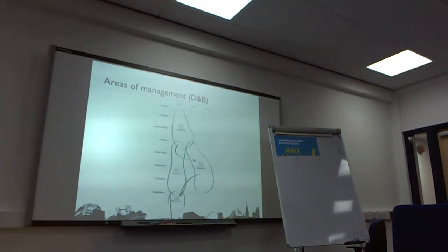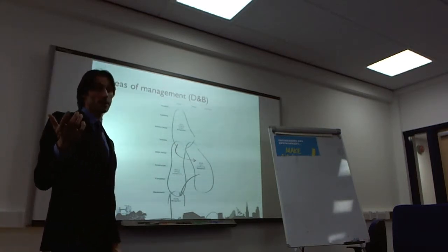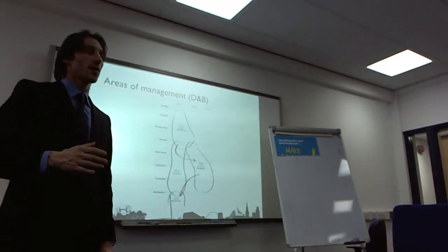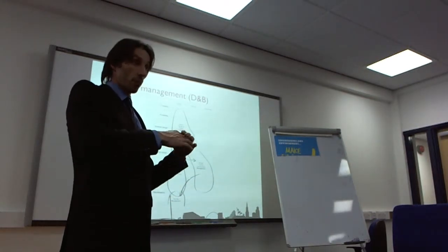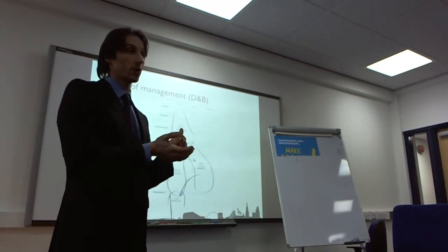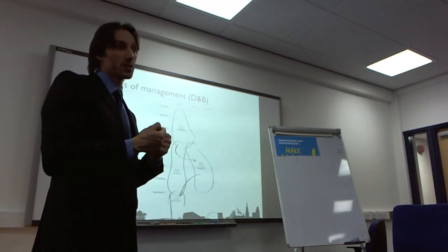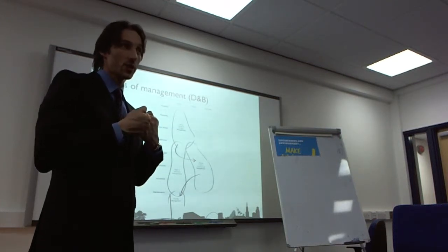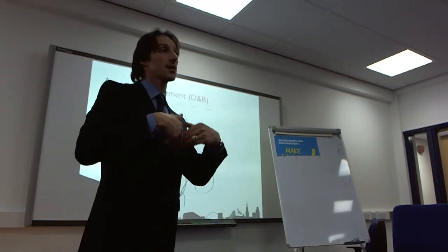But if you start looking at design and build situations, do you all know what design and build is? You do? You don't? Okay. I guess so. The traditional procurement mechanism is the one whereby you complete a design for a building, and then you produce some documents that help the contractor give you an idea of the cost. Then they give you their estimate or quotation, and then you select the contractor on the basis of that. Then you select one, and they start building.